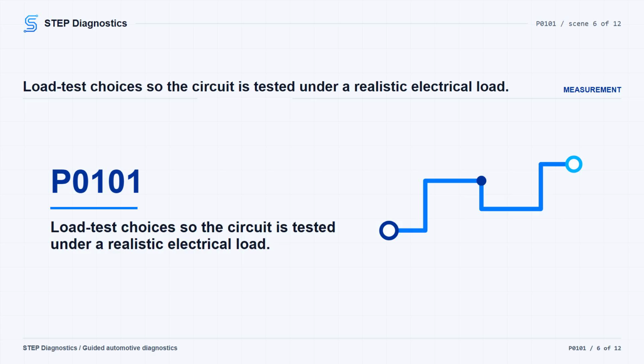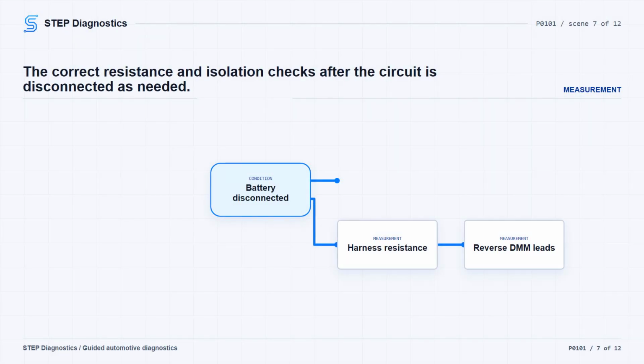Ground circuits should be checked by measuring voltage drop while the component is operating or being commanded on. Use an ohmmeter on ground circuits only if the battery has been disconnected. On most small diameter, 18 gauge and smaller wires, and for most wiring harness circuits, expect less than 2 ohms. Keep in mind that a standard DMM ohmmeter's low resistance resolution, approximately 0.1 ohm, limits its accurate use to circuits carrying less than approximately 5 amperes.